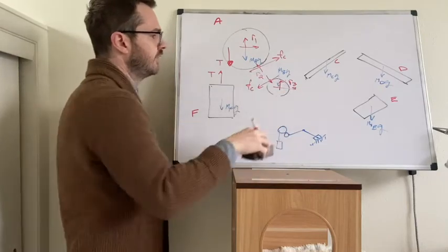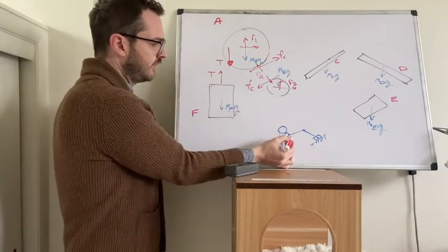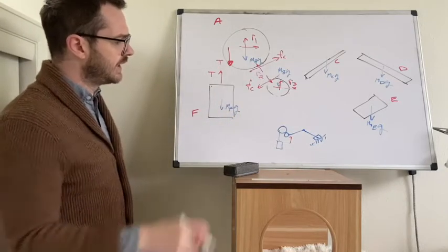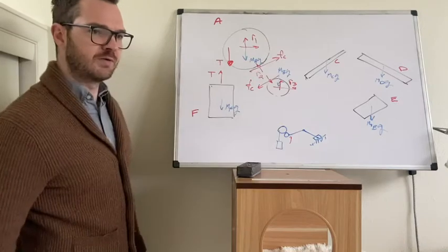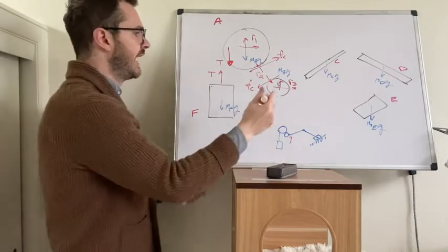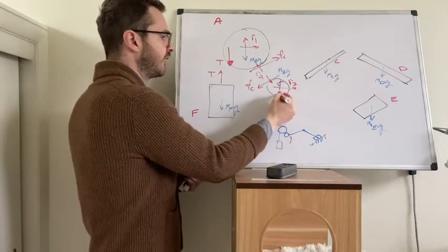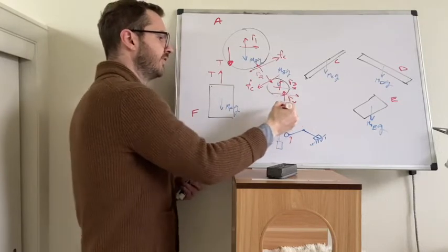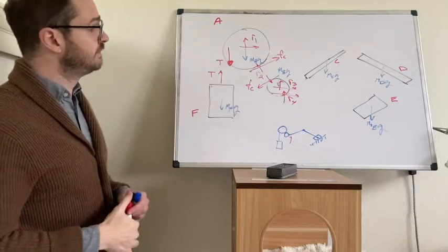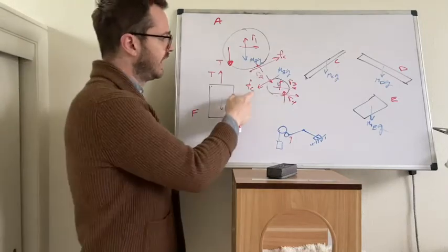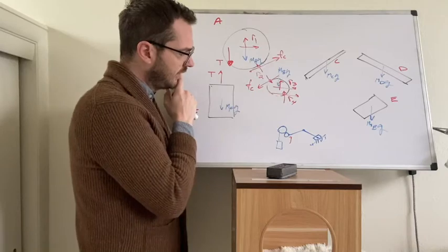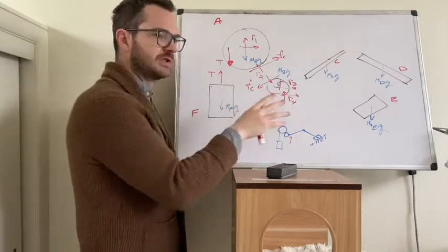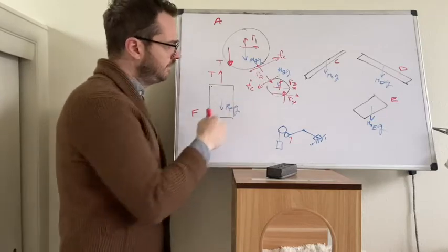And then also, there are pin joints. There's a pin joint there at that connection between the smaller disc and the first of the connecting rods. There's a pin joint there as well. So at that pin joint, I'm just going to draw it like this. There is another set of reaction forces, R4. I think that's good for the little disc. Again, unless there's something else external acting on it, or if there was friction, something like that. So I think this is okay.